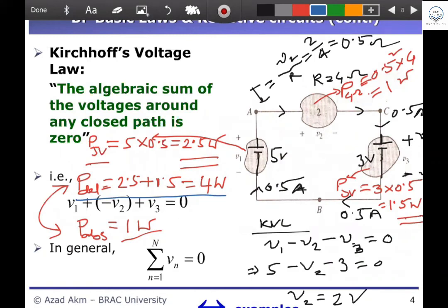You think there's a voltage source and a current source, so these all deliver power, so I add them, and resistors all absorb. Not necessarily. That's why this method is not correct for proving the power conservation rule, that all batteries and current sources deliver power and all resistors absorb. This is not true. You cannot find each battery or current source power individually, add them and call it delivered. So what is the right way? That one I'm going to show you.